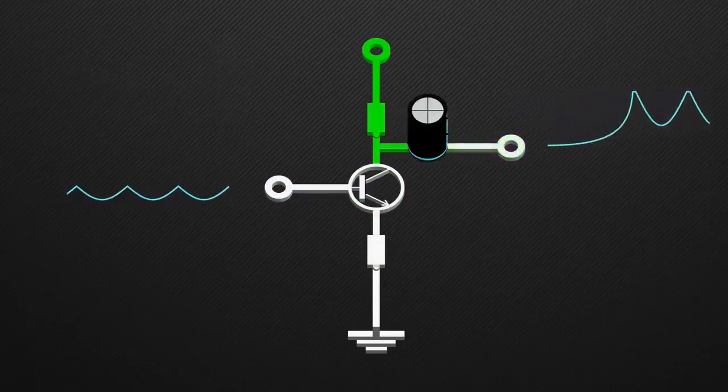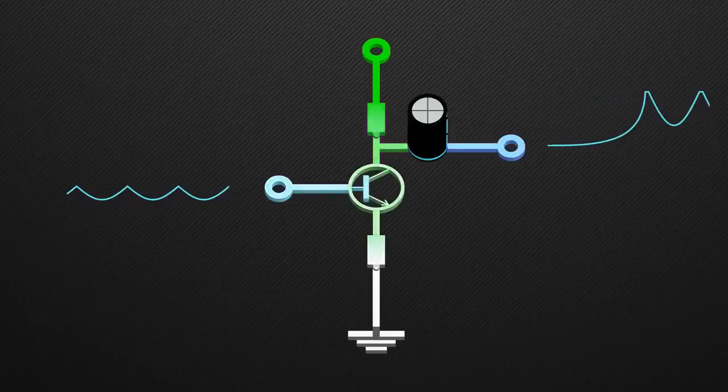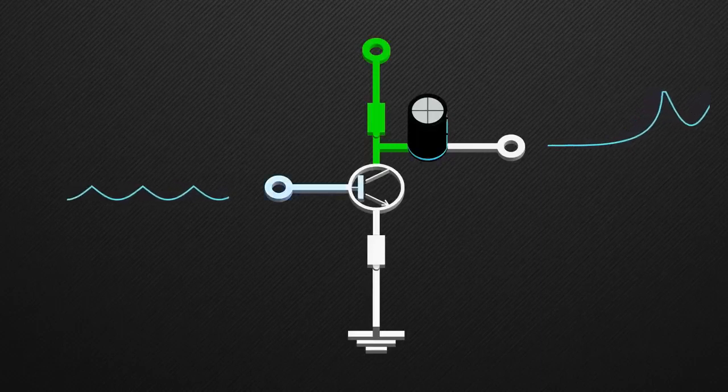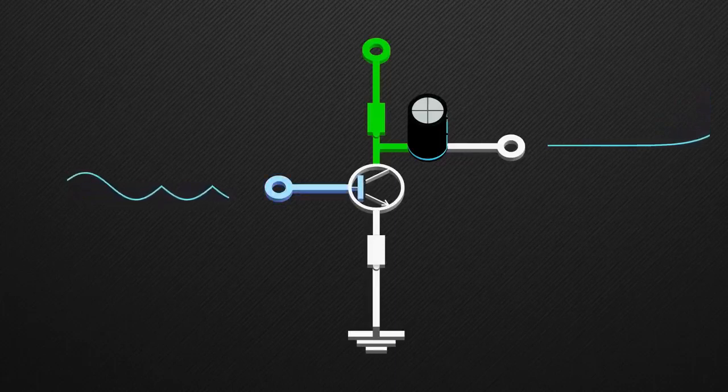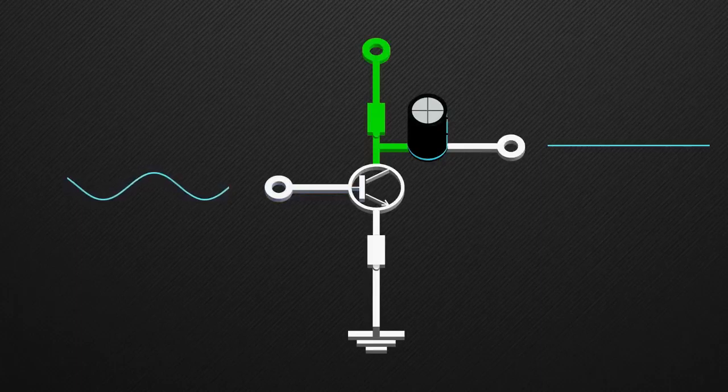At last, we add a capacitor to remove the DC bias and get the amplified input signal. You would know that a transistor requires 0.7 volts or above at the base to turn on. Thus, this circuit cannot amplify voltages below 0.7 volts. To make this actually work, we need to add a DC bias to the input signal, such that the input signal is always above 0.7 volts.